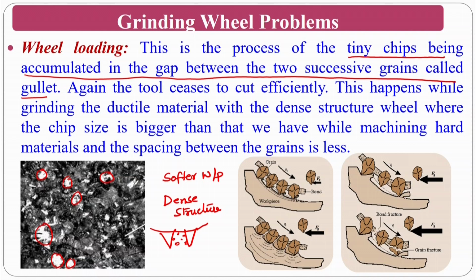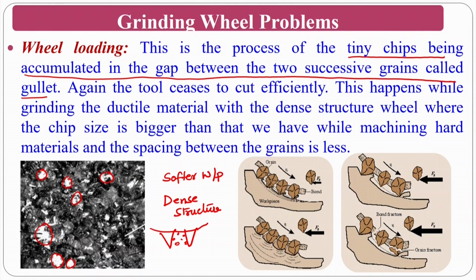In that circumstance, wheel loading takes place in very little time, because the material removal of the softer workpiece is very high. That is what you can also see here, how the material is occupying the space between two abrasive particles. Okay, so this is about wheel loading.